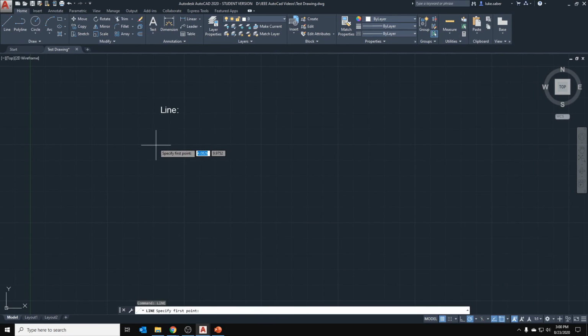You can specify the first point by clicking, or as you can see there on the screen, there's two text boxes. You can do coordinates on the XY system. There aren't any degrees, it's X and Y. So if you click tab, you can tab between those if you want to do very specific spots on your drawing. However, I'm just going to do a line here by clicking the first point, and you'll see once I've done that, it's giving me a length and an angle. So let's just humor ourselves here and do 50 degrees and make it 3.25 long.